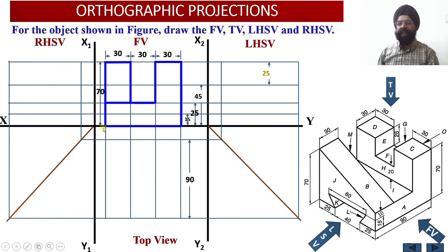and corresponding to this surface over here there will be one dotted line at a height of 15 millimeter from the bottom. So 15 millimeter above the bottom we are going to observe a hidden line or a hidden edge. So it is this cut, and this cut is running through and through.